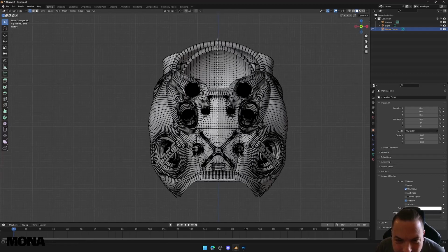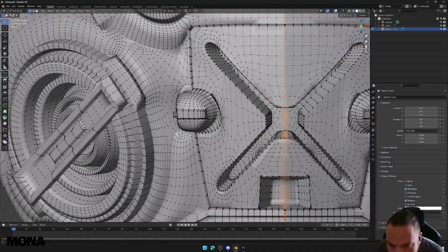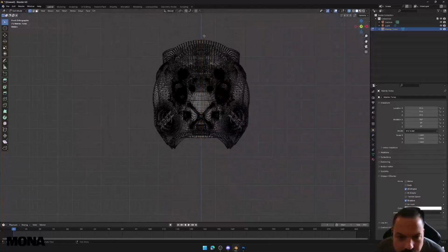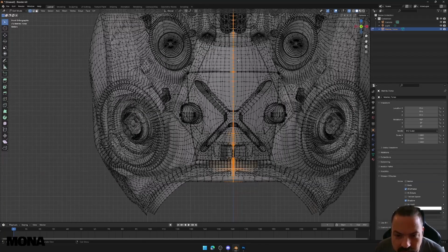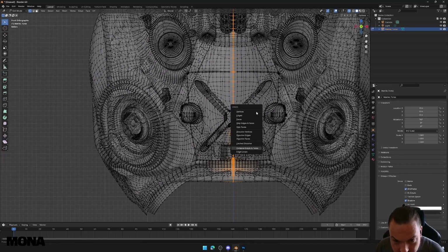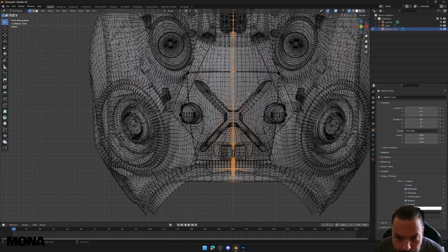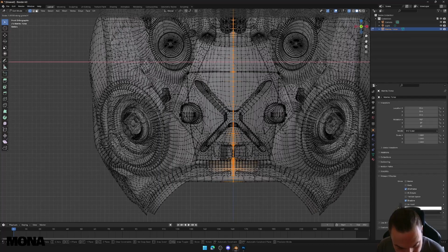That's how I roll. Let's go down those. Do it again. Actually, holding Alt and left click will select edge loops. Once you have selected, press 1, and it'll go to that, and then I'm just going to scale X 0.